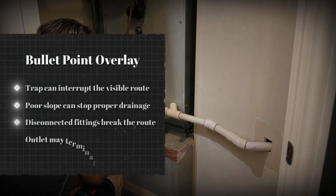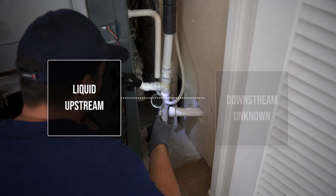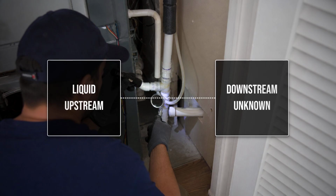A condensate system can have a trap, a slope problem, a disconnected fitting, or an outlet that terminates where the homeowner cannot easily see it. Adding liquid without understanding the path could put more water upstream while telling you nothing about the condition farther downstream.